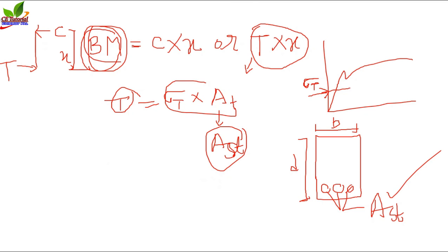Now, in brief, we can say that the applied bending moment created by the external load equals the compressive force into x, or we can say sigma c, that means compressive stress in concrete, into area of concrete into x.